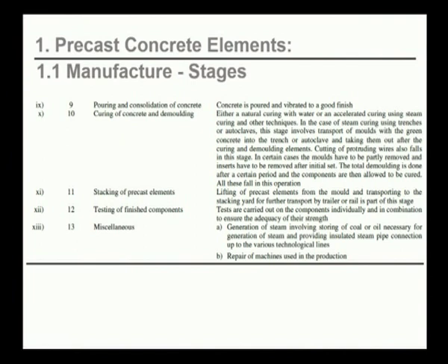The 11th stage is stacking of precast elements together. Lifting of precast elements from the mold and transporting to the stacking yard for further transport by trailer or rail is part of the stage. Then comes testing of finished components. Tests are an important part because without testing we cannot use them for structural uses. So tests are carried out on the components individually and in combination to ensure the adequacy of their strength.